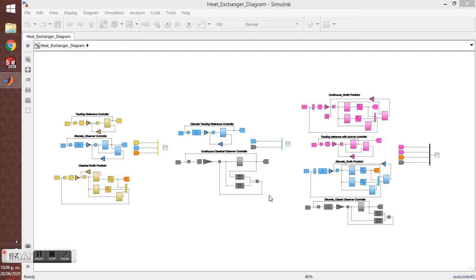Additionally, a response time has been implemented for the plant, taking into account that in real life all plants have a response time before they are turned on and put into operation. This generates some lags in the graphical response that are effectively solved with a Smith predictor.